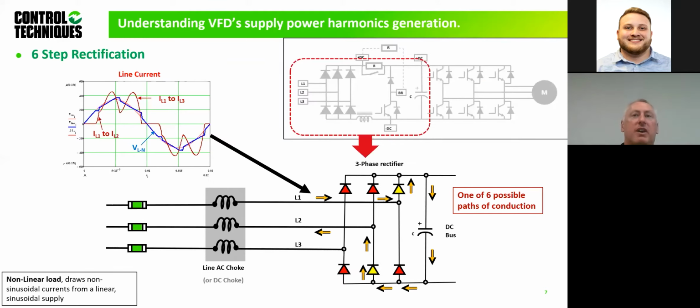So, what do we get on that front end? This is what I'm more concerned about for this presentation: what does this diode rectifier with a capacitive load do? And if you dare enough to put a scope or a clip-on meter on there, you will see the current is very peaky. It's not nice and sinusoidal, purely because of the diode rectification and peak charging through the capacitor. With the diagram on the left-hand side, you will see how the diodes commutate from phase to phase and produce this double peak each half sine wave of current.